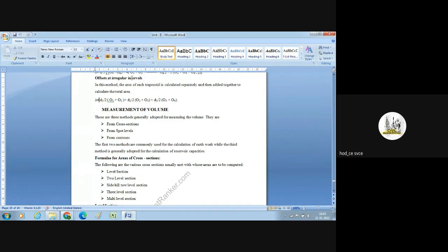Next, now the meridian line was shifted from the point A to C. Based on the line C, we take the departure distance from the shifted meridian line. But for M1, M2, M3, M4, we have to take the meridian that we decided on. From there itself, you have to take the distance.